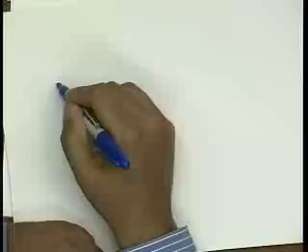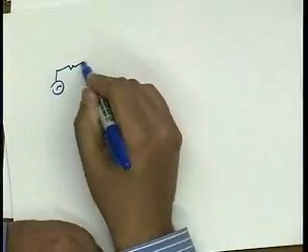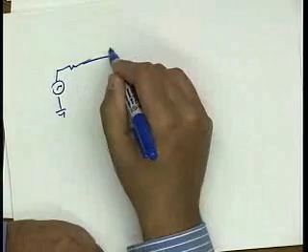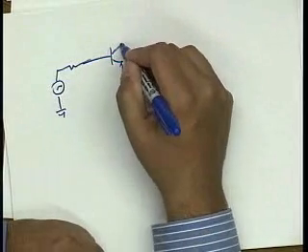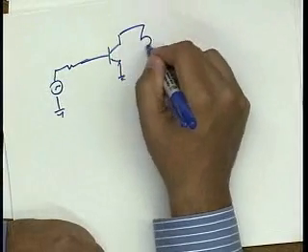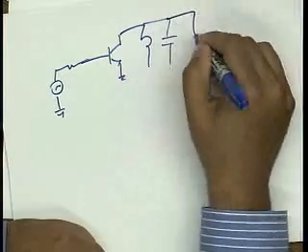Yes. The problem with CS or CE amplifiers was that there was another Miller-affected capacitance in the input. So the question: do we need another inductance on that side to tune it out? Very good question. Okay, so the question is, I'll repeat it. We just kind of ignored the input capacitance, but remember, for common source amplifier, that input capacitance was actually quite problematic. So the suggestion is, can we do the same thing at the input to tune out that capacitance?